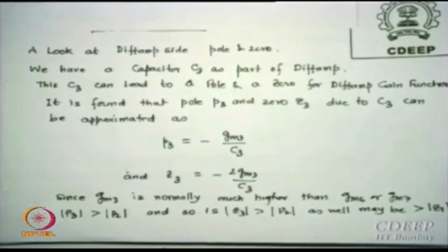One will go 20 dB, and near it the other will start coming down, so for each other they are not of any use. So essentially we may now say, if my P3 is much larger than P1, P2, and Z3 is also much larger than P2, which I got in fact, as I say 900 odd megahertz, then the use of these poles and zeros is not of any relevance in further calculation, though we may have to evaluate to verify, okay.